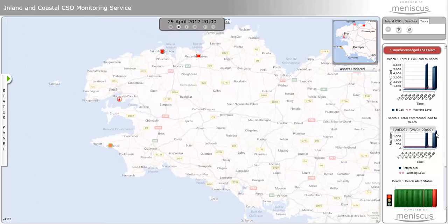We have incorporated the results of the beach modelling into a much more complex calculation system, so that we are applying the modelled scenario for every cubic metre of discharge from a particular CSO, using the outputs from that modelling in a real-time application, and combining that with local tide conditions. And that's the system which we actually have live with Anglian Water at this moment in time.